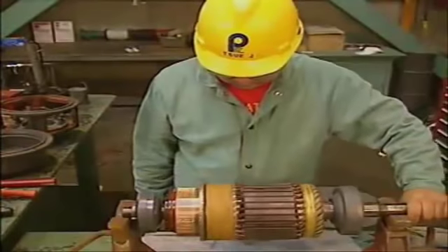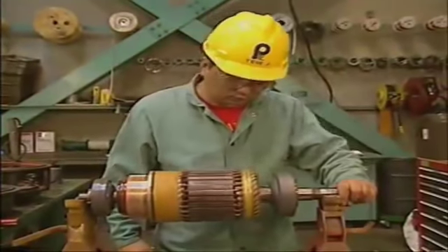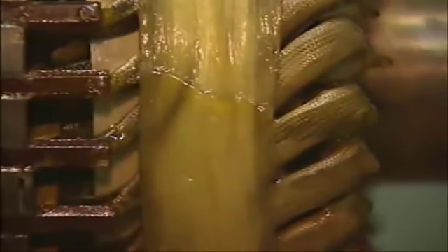vacuum as necessary. The armature banding, which is the wrappings of wire or string around the armature core, should be checked to make sure that it is tight and intact. The backs of the coils, which are the ends farthest from the commutator, should be inspected for damaged areas, and the insulation should be checked to make sure that it is not cracked, chipped, or broken.